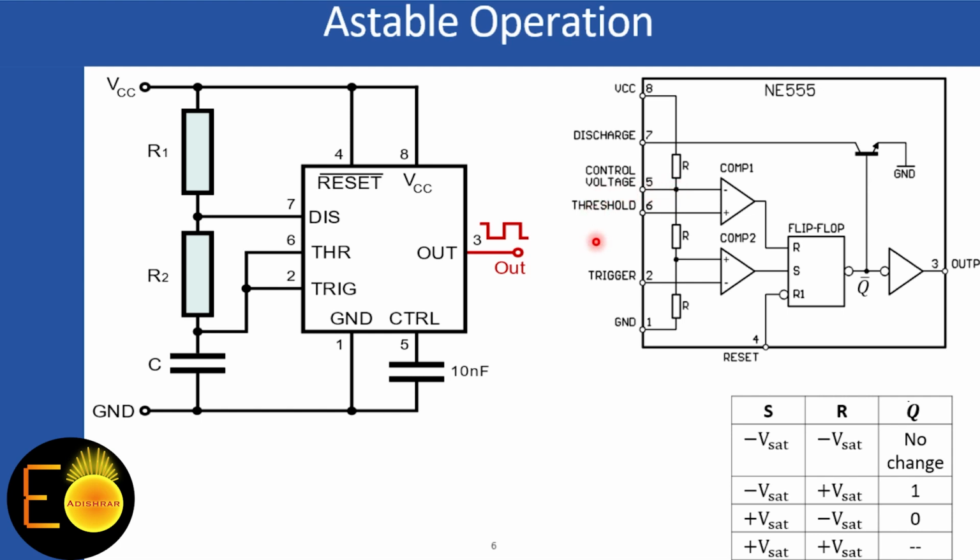And when the capacitor voltage becomes greater than the dynamic voltage, at that moment the pulse width at the output is also changing. On the other hand, when the capacitor is discharging, during that time the potential at this point is also changed, because right now I have applied a sinusoidal signal, and that's why the next time the capacitor needs to reach a different voltage than it reached in the previous case.